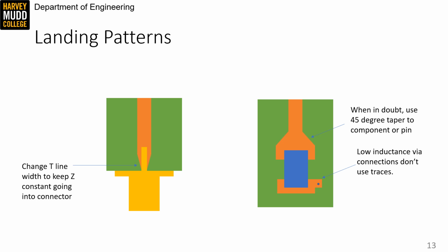So tapers or expansion of lines to mate with pads and components are called landing patterns, and they're really important. You can usually get landing patterns from component designers, and especially I've had great results asking connector designers for landing patterns for different board stack-ups. They have been really obliging about it. Sometimes even assigning an application engineer directly to me to make a custom landing pattern.